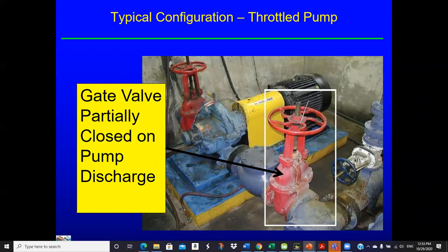Well, then you call the gate valve manufacturer and say, hey, send me a CV curve for your gate valve of CV versus position. They say, no, we don't publish it. What do you mean you don't publish it? Our valve should be either full open or shut. There's no point. They'll tell you the full open CV, but they won't tell you anything in between because they don't want you using it for that.